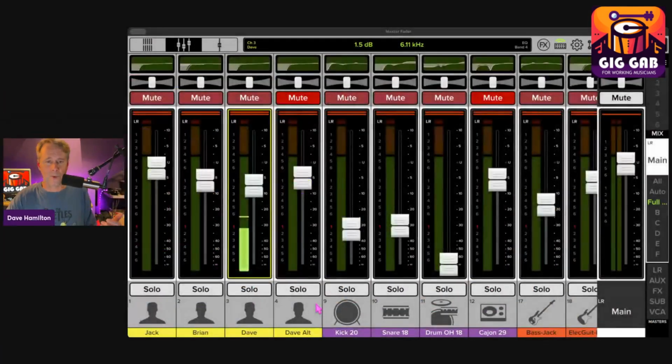After that, you do it for all the rest of the instruments, of course. One thing I will note is that with drums, especially a bass drum, in order to really make the speakers, the subwoofers especially, activate, you're going to want more gain out of it than I would with a vocal mic. Every time the bass drum is hit, I want it to go a couple of dB past unity.